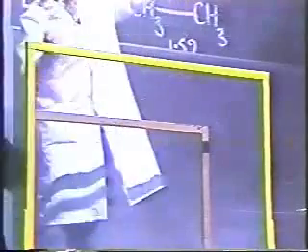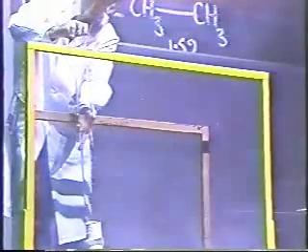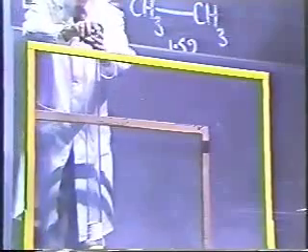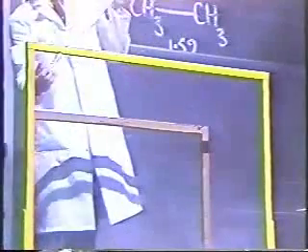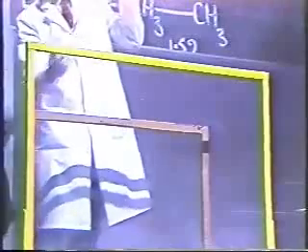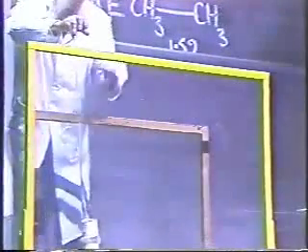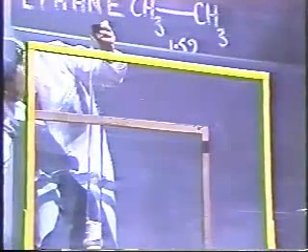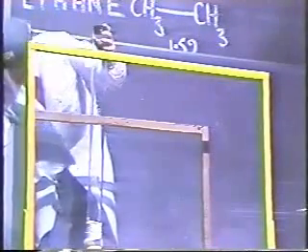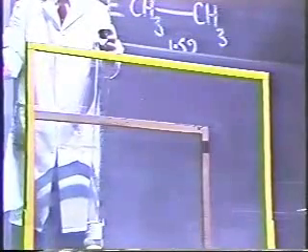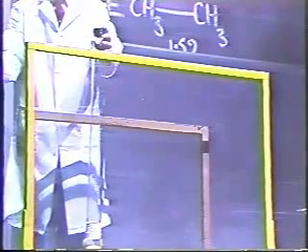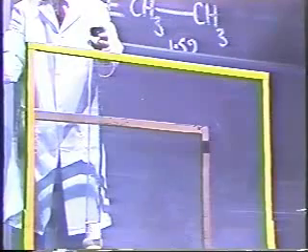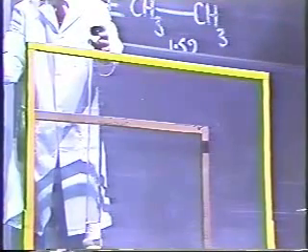because the burning of the first portion will, of course, generate pressure, which will tend to compress the remainder. And if you compress a gas, you generate heat. I don't know if anyone ever pumps up a bicycle tire with a hand pump now, but in the days when they did, they would notice that the pump gets warm. If you compress a gas, you generate heat. And adiabatic compression, so rapid that the heat generated has no chance of escaping, can raise the temperature hundreds of degrees centigrade.